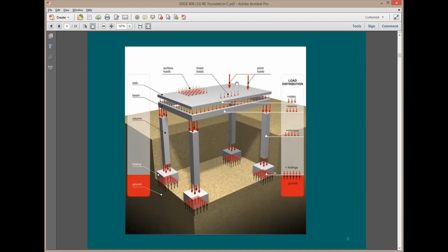So what's going to happen? The slab is going to be taking this load and distributing it to be kind of uniform load when it comes to the surrounding beams. So first, the load is going to be coming from here, this applied load, with the self weight of the slab and any other additional dead load that you'd like to add. And then it's going to get transferred to these 4 beams, and then the beams are going to be supported on 4 columns. So if you think here about the beam, like the standard way that you used to do in structure analysis, you take this beam from here to there, another beam from here to there, and then you look at this uniform load, you do the analysis, you find out the reaction from both beams.